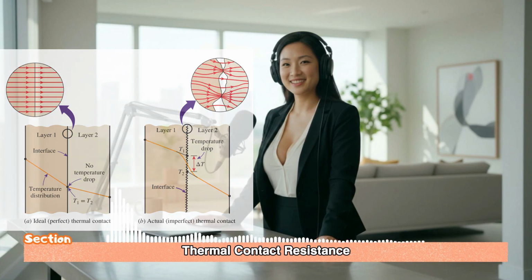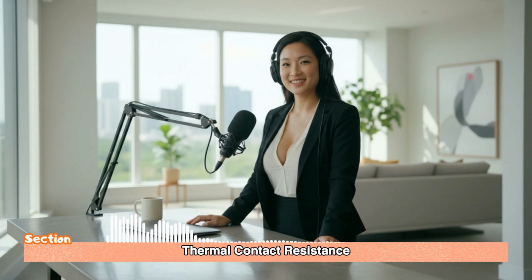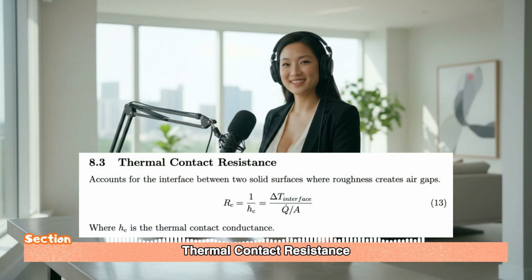So how do engineers even quantify this? It seems like it would depend on how rough the surfaces are, how hard you press them together, all sorts of things. It does. So the total heat transfer across that interface is a combination of conduction through the few solid spots and conduction across all those air gaps. We quantify it using a term called thermal contact conductance, HC. Okay. And our contact resistance, RC, is just the inverse of that conductance.